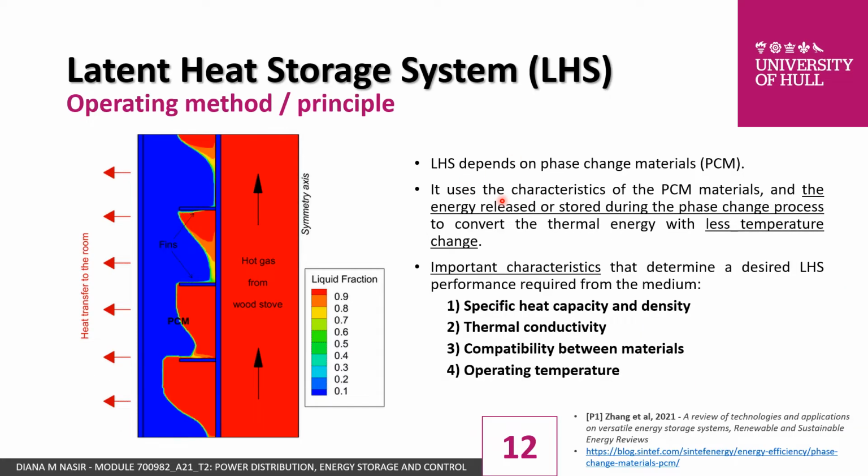Latent heating uses a reverse fundamental to sensible heating, where the energy is stored and released during the phase change process with a very nominal temperature change. However, the system performance will depend on the density of the medium used, the specific heat capacity, the thermal conductivity, the operating temperature, and also the compatibility between the mediums.